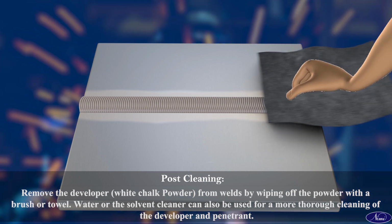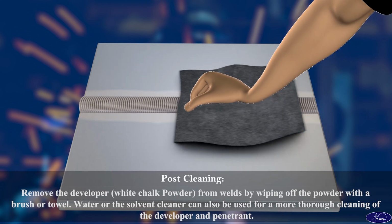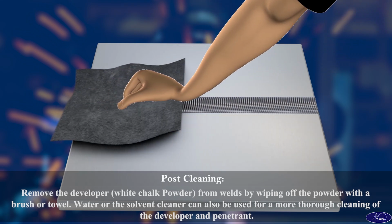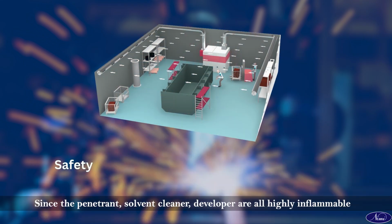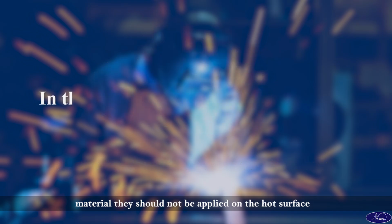Post-cleaning. Remove the developer, white chalk powder, from welds by wiping off the powder with a brush or towel. Water or the solvent cleaner can also be used for a more thorough cleaning of the developer and penetrant. Since the penetrant, solvent cleaner, and developer are highly inflammable materials, they should not be applied on a hot surface.